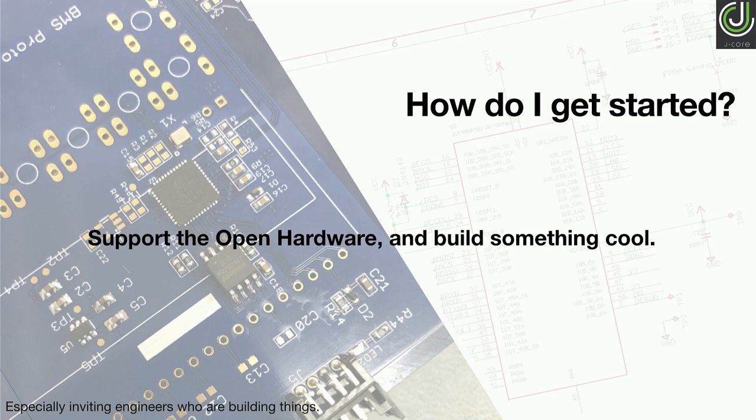One quick question. You said you taped out with the SkyWater 130 nanometers with only up to 85 megahertz frequency. That is not high, I think. And I wonder how much frequency you can get on the J1 on iCE40. Yeah, so J1 on iCE40, just synthesis without doing any optimization, you get about 14 megahertz. So it's really small, right?